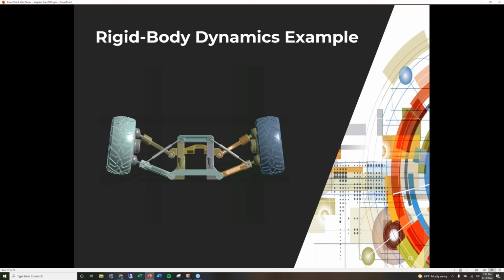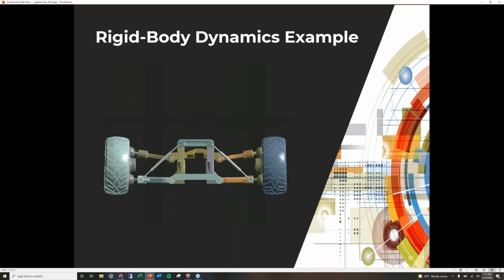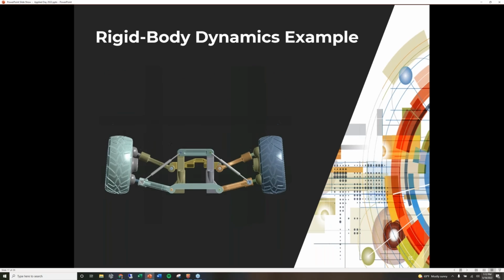And so to me, the suspension looks a little bit undertuned. We're sagging a little bit, lower than we probably should, and we might be bottoming out. So this suspension could use a little bit better tuning.